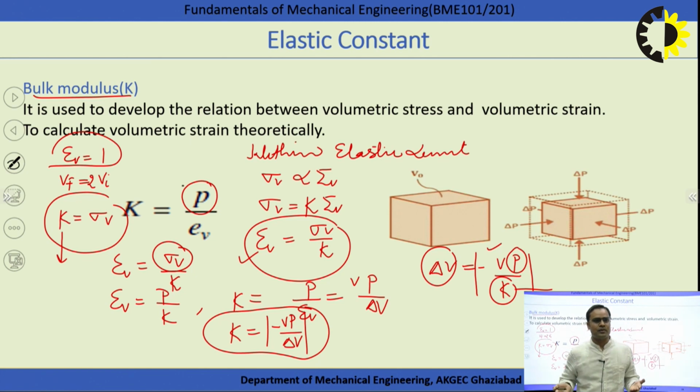So we are able to calculate how much extra volume we have to put inside the cylinder to maintain the same pressure. Generally we can easily observe that an older cylinder definitely has a higher weight, because there is an expansion of the walls, and when the expansion takes place, we have to put in extra volume to maintain the same pressure. So definitely we can observe an older cylinder always has more weight than a newer cylinder, right? I hope this concept is clear to everyone.